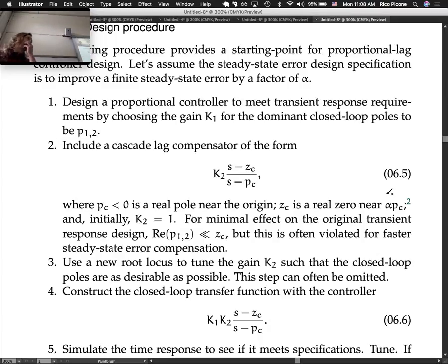That factor doesn't exactly give you the perfect steady-state error improvement that you're looking for in certain cases. If you have a position static error constant, KP, if you remember that, it's a little bit different than just this ratio.